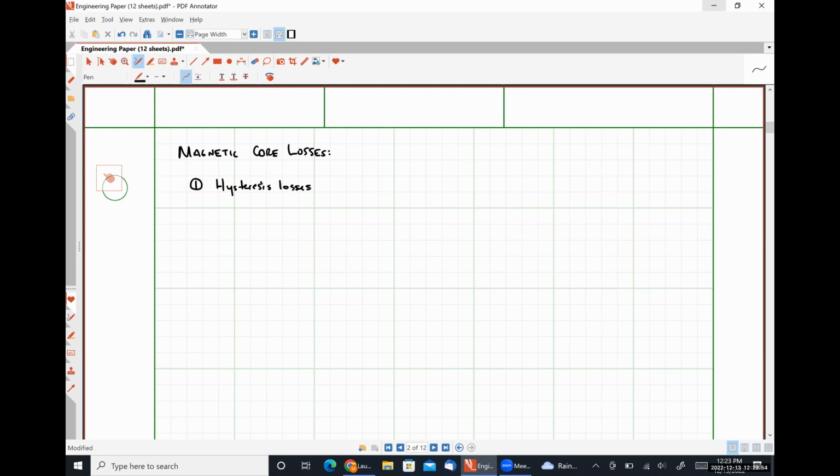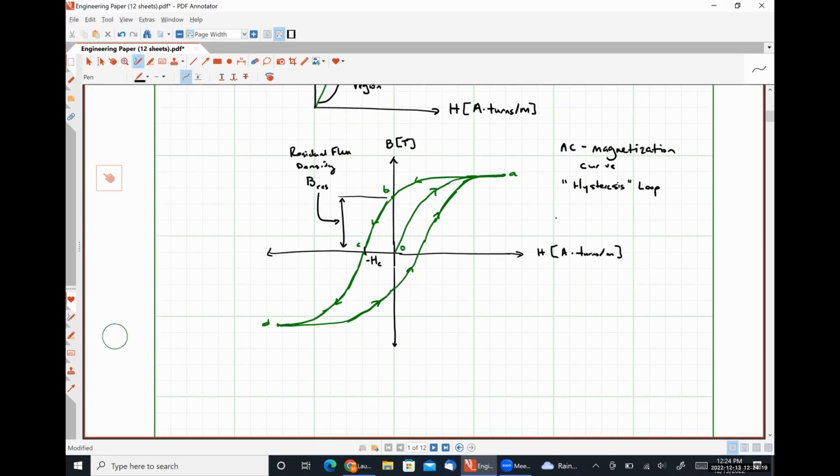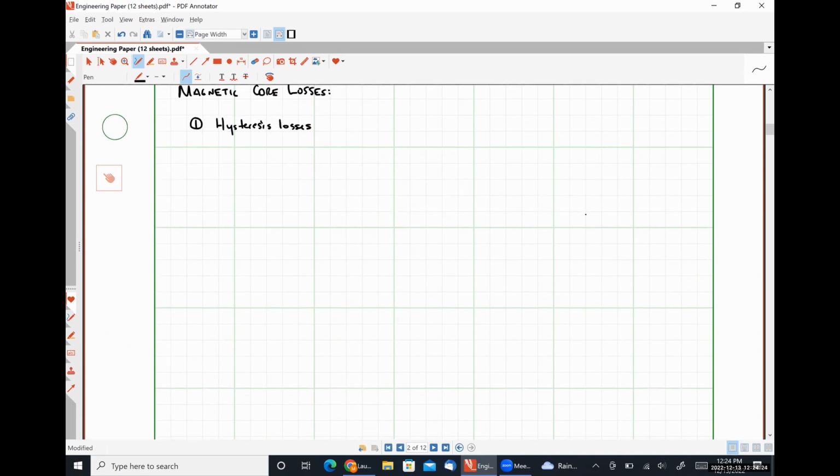As we discussed a little while ago, when a magnetic material is subjected to an external magnetic field, the domains of the material tend to align with the direction of the applied field. It takes energy to cause those domain fields to rotate into that direction. That energy is the hysteresis loss. Effectively, the hysteresis loss is the area inside of this funny looking curve, okay?